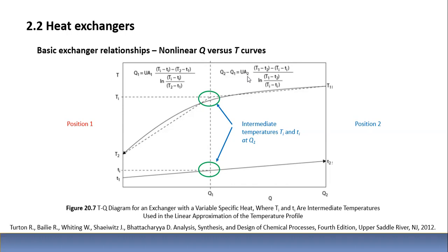That's what you see there, the same U. The area changes because this is another portion of the exchanger. It has a different area along this length, and this portion of the exchanger also has a different area. That's why you see A1. So at the end of the day, that gives Q1 for this portion of the exchanger, and this other portion gives us Q2. Adding these two, we'll have the full heat load of the exchanger, doing a zone analysis, an analysis by zones.